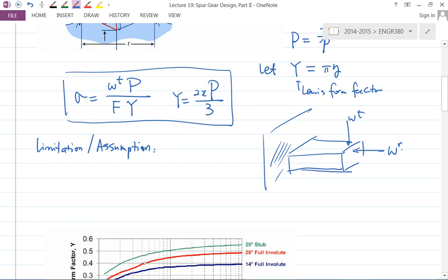Compressive stress, right? What direction is the bending normal stress on the cutting cross section? Where does it point to? This way. And where does the compressive point to? That way, right? So if you're really looking for bending normal stress on a cross section, theoretically, what do you need to do? You need to use the bending normal stress from this one, and then subtract this guy here, right?